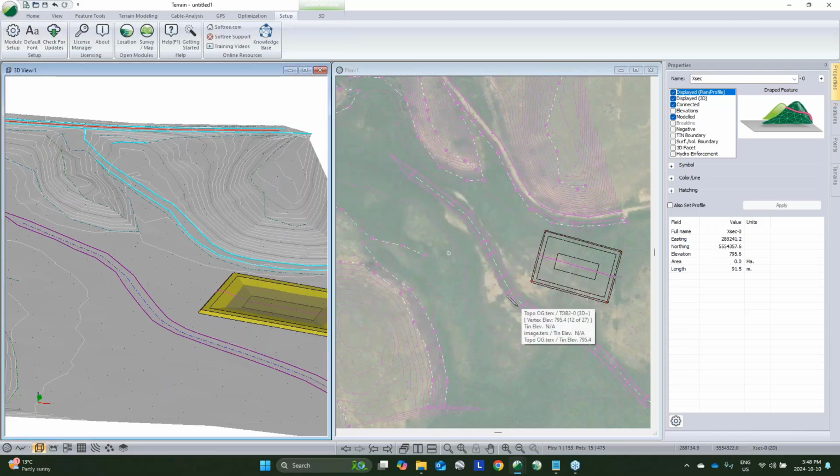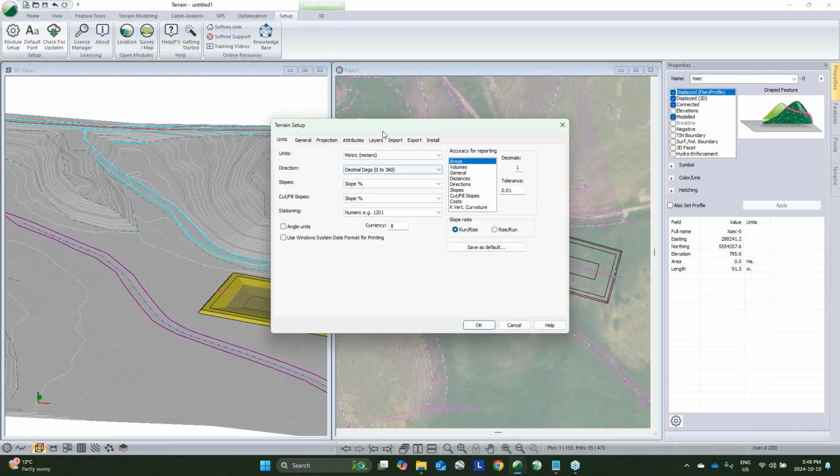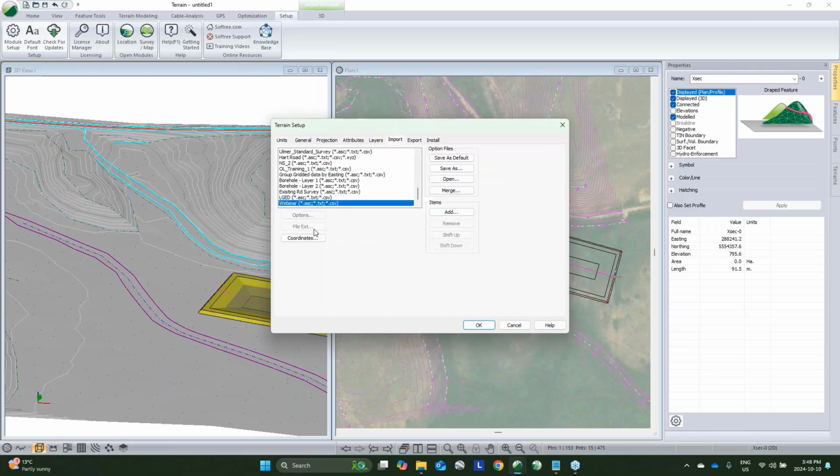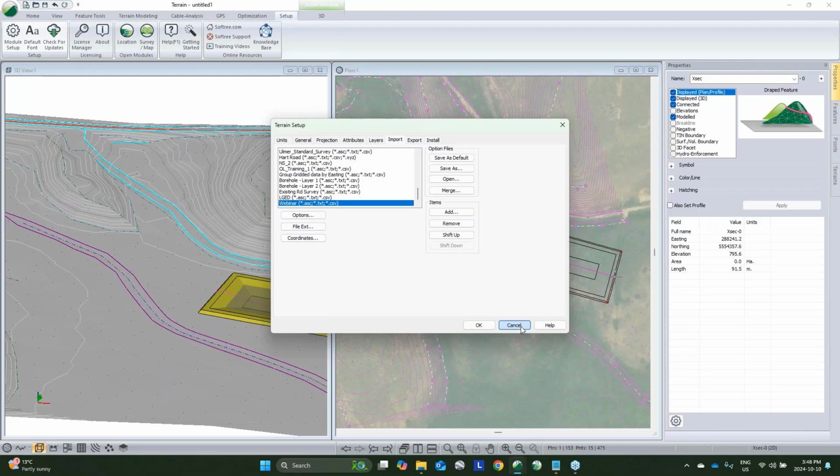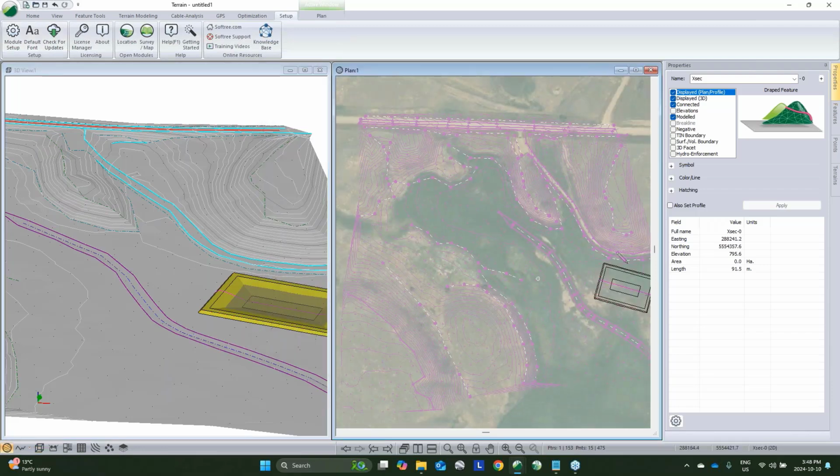Caveat of thinking about it, in this case, with that IOP that I have set, my default is set as a black dot. So if I were to have brought that survey data in and noticed a bunch of black dots, it's probably because I don't have a point code named to match it. We can click on it, see the name of that actual feature, and if it's something that we expect to see again, we can update that IOP and hit save as default again. So absolutely can save it and can share them too.